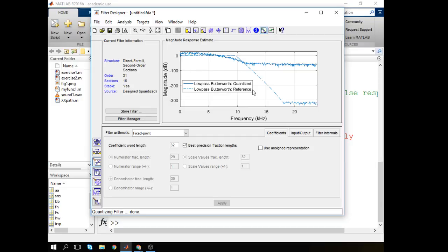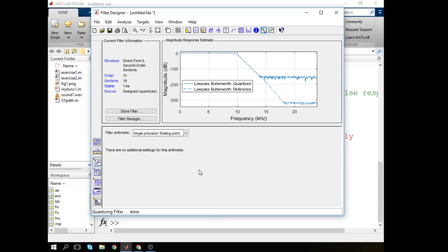So basically, but anyways, you should be able to actually check what is the difference between. Okay, so yeah, this is a good example actually. Compared to single precision floating point, doing it double gives you about 300 dB here, but when you go to single precision floating point, this filter basically cannot do more than 150 dB attenuation. Although 150 dB attenuation is a lot. It's already a lot of attenuation. Okay, but that was something a little bit extra curriculum.